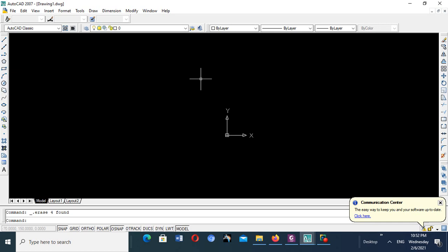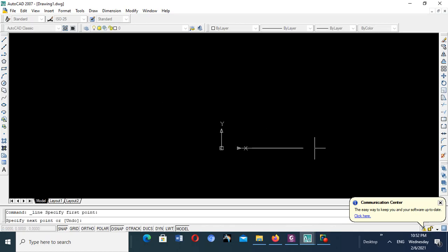do more work. Now we know how to draw a horizontal line, we know how to draw a vertical line. Now all line work you can practice. Right? I start from there, then I go to the origin, the line command is there, then I go to the origin, I press, then I want to go in that direction 100.